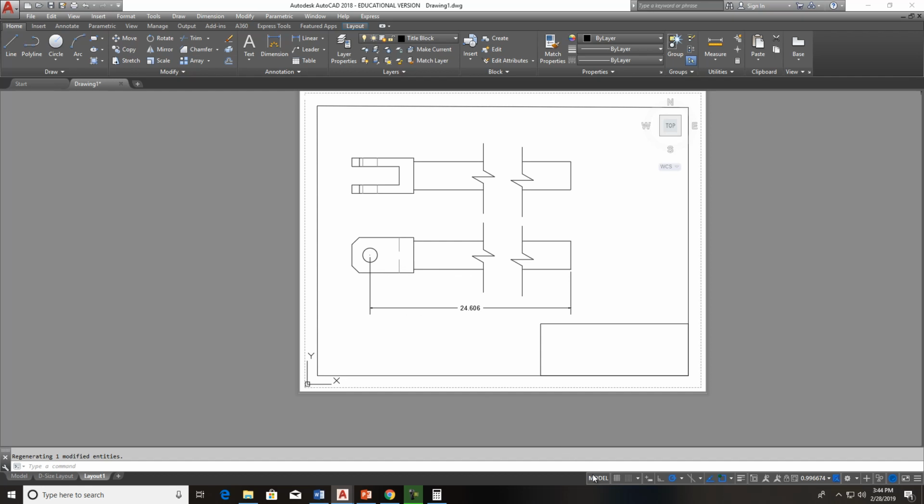Now, I am seeing my line type scale, so let's go in here where we're model LT scale, and 1. Sometimes the scales of the line types don't look the same as what they do in model space to paper space.